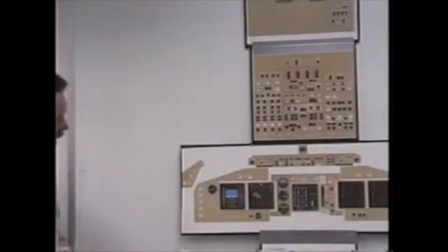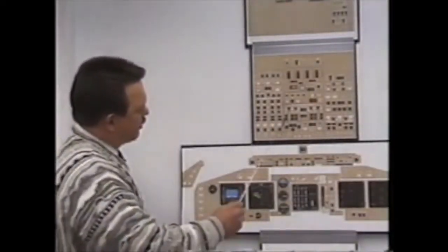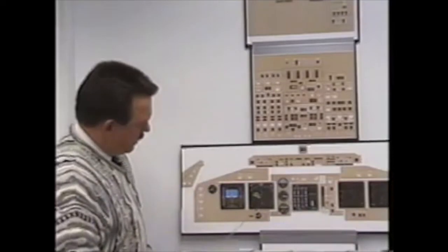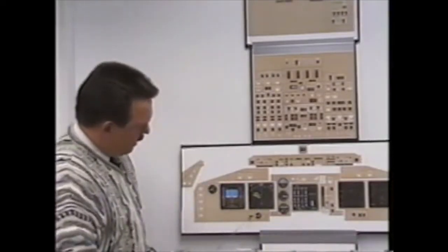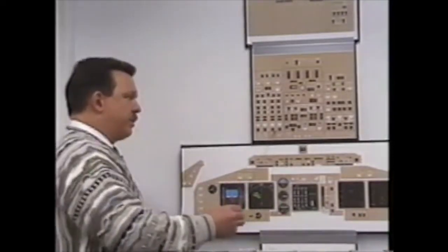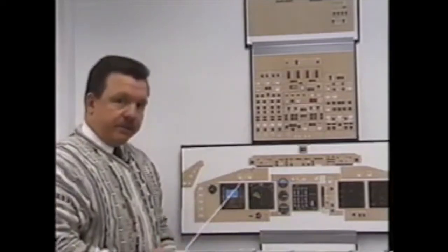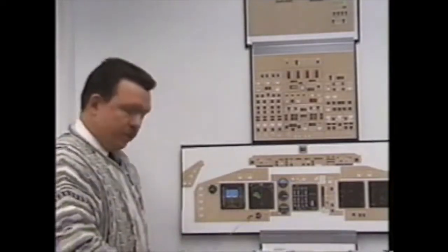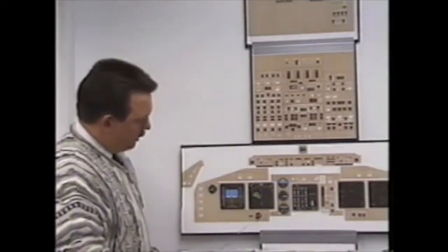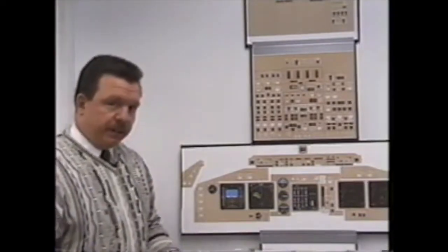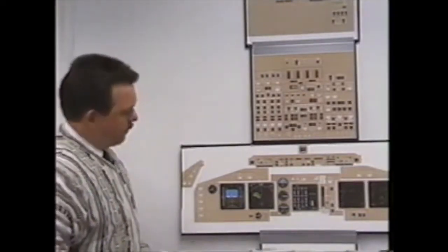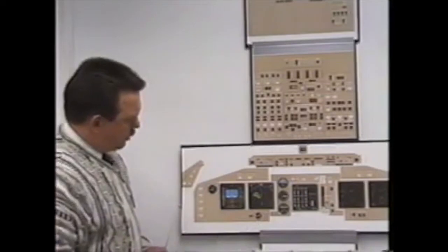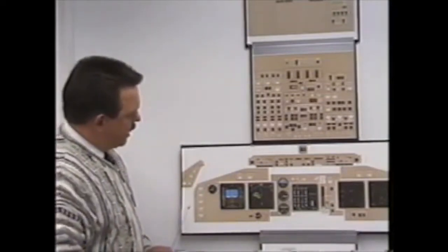Further discussion on your brake system with reference to your hydraulic control panel on the overhead panel, your normal brake accumulator, and your brake source light. We'll simulate that all 4 hydraulic systems are depressurized, and as a result, the brake source light will be illuminated. Your brake accumulator indicates pre-charge pressure. The underlying number here is 750. We'll show that it indicates 750.